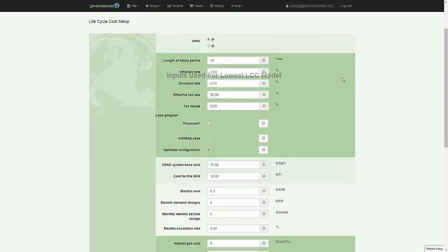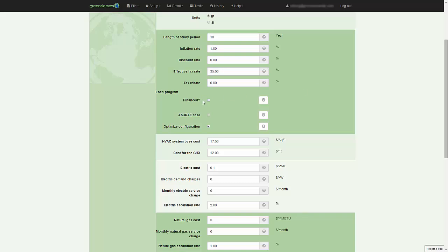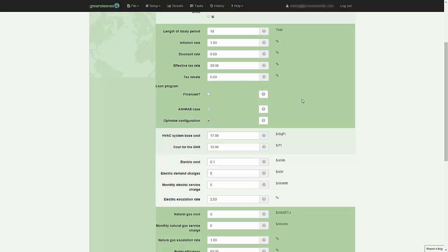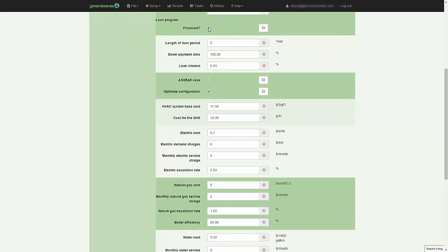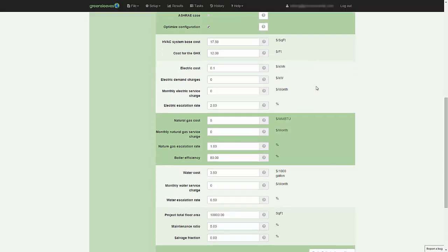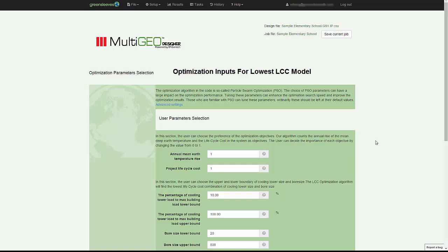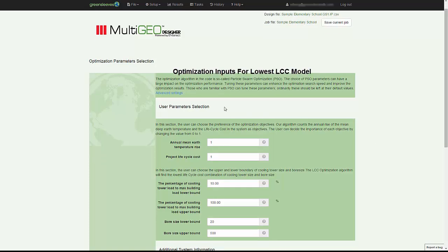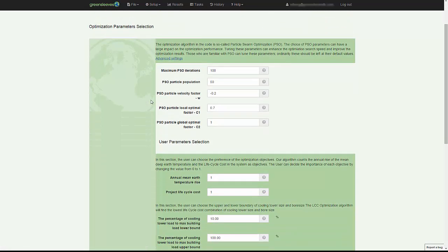Part of the optimization process in design is looking at how to prepare a system configuration with the optimum bore field size and tower size to deliver, say, the lowest energy cost, lowest first cost, or lowest period cost. In the period, it's kind of a life cycle cost, but it's a study period that says the combination of energy cost and first costs reaching the lowest point. And so certainly you can drive to your lowest energy consumption or your lowest energy cost or the lowest study period cost. And that is often what our clients like to see is how we converge to that optimum financial situation.